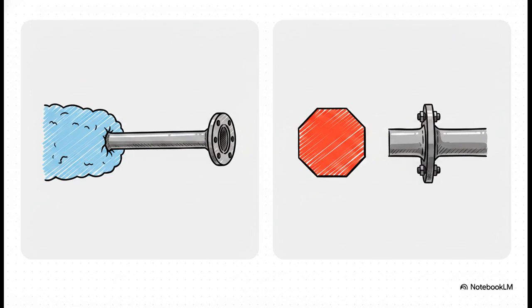So, the long welding neck acts like an extended arm reaching right through the thick insulation to give us a clear, accessible connection point. Conversely, a blind flange isn't connecting a pipe to another pipe at all. It's actually a solid steel plate used to securely cap and seal the end of a line. Think of it as the ultimate stopping point in the system. The whole shebang just stops right there.